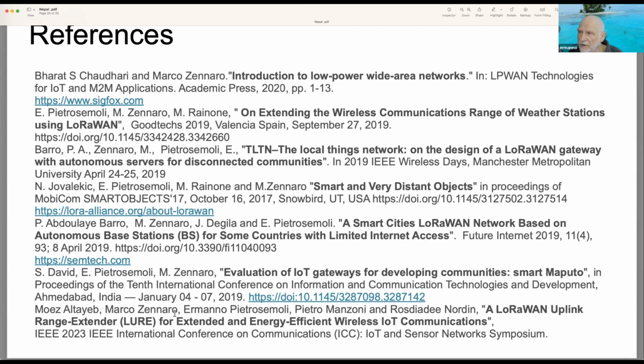No matter, you deploy your gateway, and your gateway will listen. Any legal packet will be transported to the network server. The network server will decide which application this packet belongs to, and will forward that message to the particular application. So you can have the same gateway serving different organizations, like one for meteorological data, another for pollution, another for temperature, humidity, another for whatever you have in mind, even for alarm, okay?